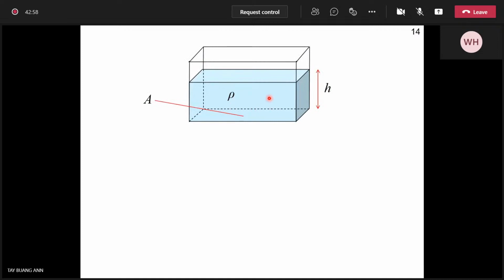And we can see it easily here. For example, you have a container with certain water. The pressure exerted by the water on this surface area here, you need to find the weight of the water, of the fluid inside, divided by the area, because this much weight will distribute over this area. So we can just find the mass using the density, right? Because the fluid does not have a specific shape, we need to find the total volume, and the density gives us the mass.